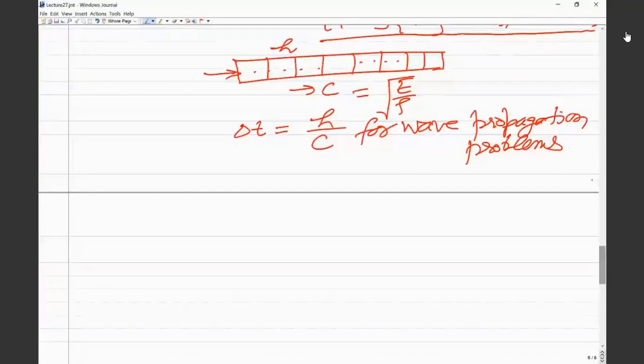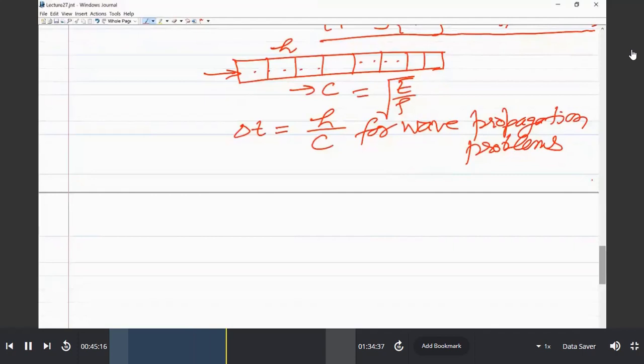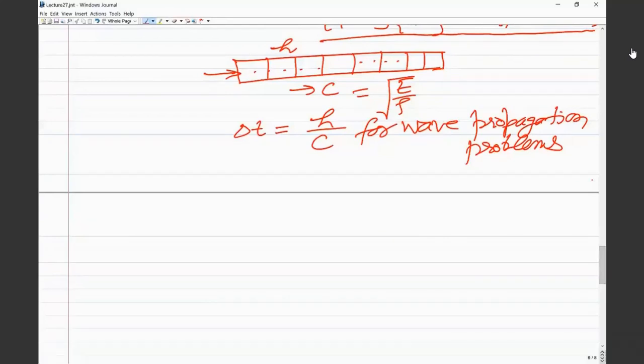They are converted into a dynamics problem, but the loading is applied slowly so that the effect of dynamic terms in the solution is minimal. The advantage is that you use the diagonal mass matrix, so you don't have to solve simultaneous equations, and you get the solution computationally much faster.